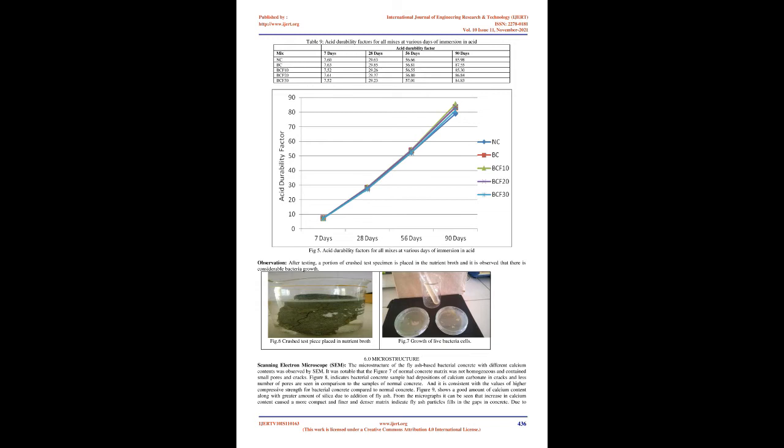After 28 days period of curing, the specimens were removed from the curing tank and their surfaces were cleaned with a soft nylon brush to remove weak reaction products and loose materials from the specimen. The initial weights were measured and the specimens were identified with number.